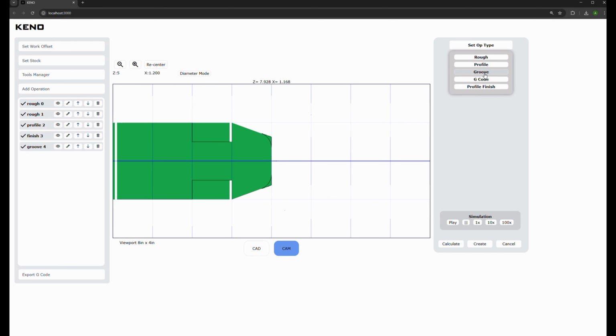We can then add, for example, a G code. I like to add an M01 and then G101 and then G01 X0 Z0. So what this does is it stops the machine. We can remove the part, clean up, and then we click cycle start, and it's going to move the tool to this point right here. That allows you to pull our stock all the way to the tool and consume less time in setting up. So I always like to do that when I'm going to run production parts.